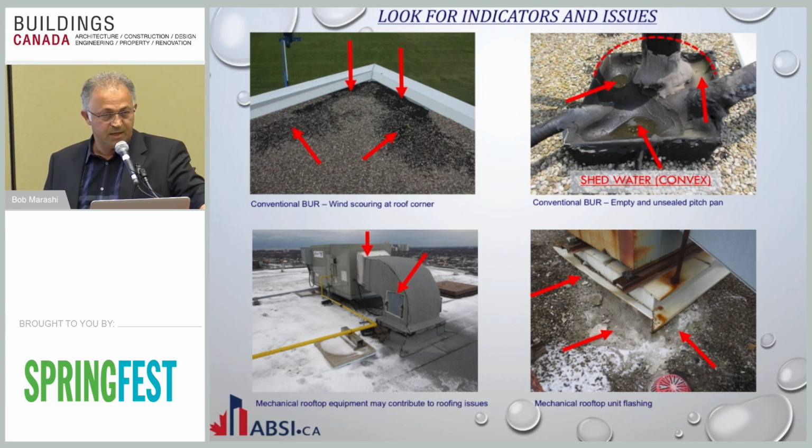Nobody does it. Not all leaks into your building are from roofs. Sometimes they're from mechanical units. Pay attention to your mechanical units. Otherwise, you've got your roofer and your mechanical guy pointing fingers at each other for a small leak.